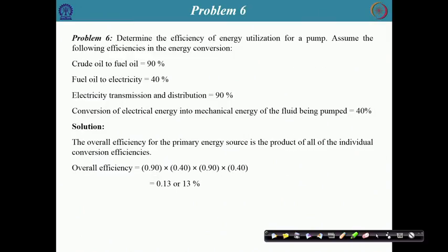Let us come to problem 6, that is, determine the efficiency of energy utilization for a pump. Assume the following efficiencies in the energy conversion: crude oil to fuel oil is 90%, fuel oil to electricity is 40%, electricity transmission and distribution is 90%, conversion of electrical energy into mechanical energy of the fluid being pumped is 40%. In industry, we operate a number of mechanical units. The overall efficiency of all units needs to be calculated to determine the